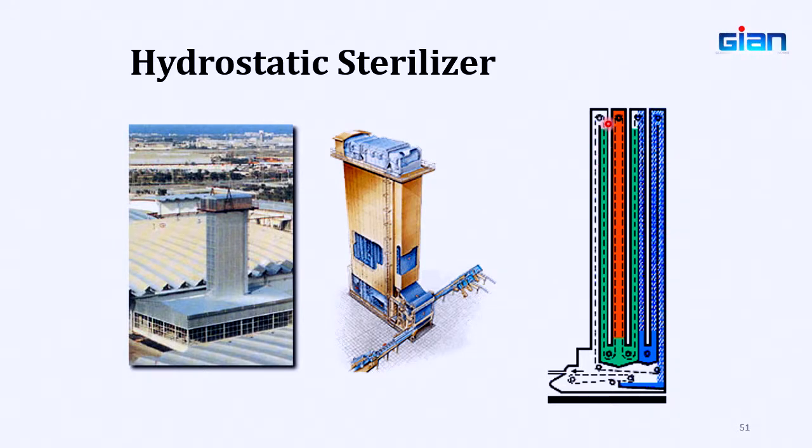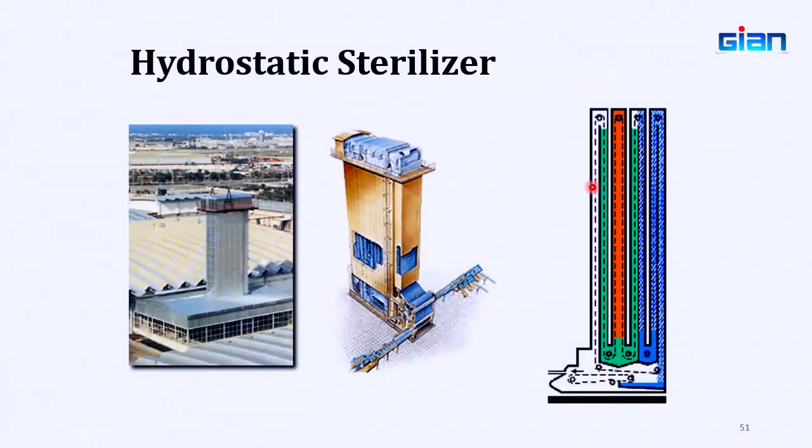And then the green one, as you see, this is hot water, okay? And this hot water column is creating hydrostatic pressure, right? You understand hydrostatic pressure? The pressure created by the water column, right? Because of that pressure, you are able to maintain this steam at more than 100 degrees C, because this steam is now under pressure. And that pressure is being created by this water column.